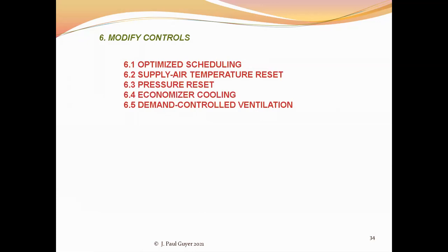You're all possibly familiar with economizers. Essentially, an economizer is a control system that controls dampers on the return, exhaust, and supply ducts to the fan.